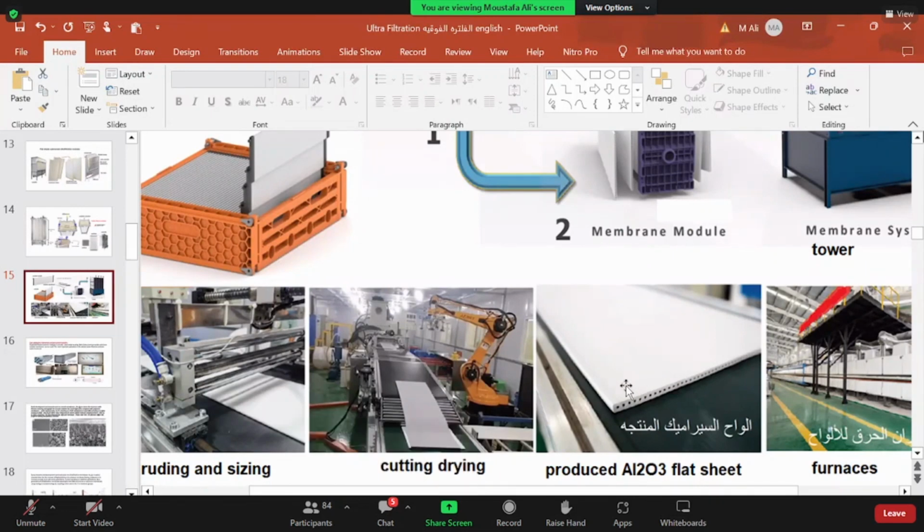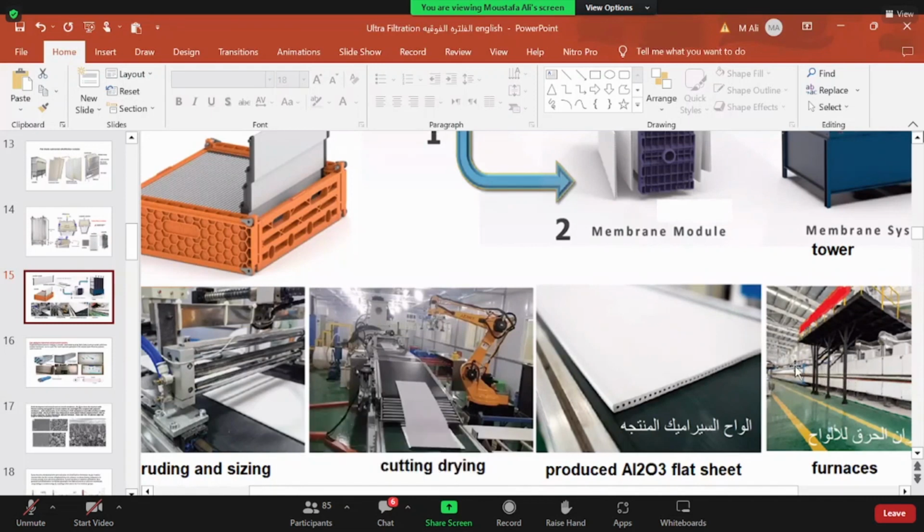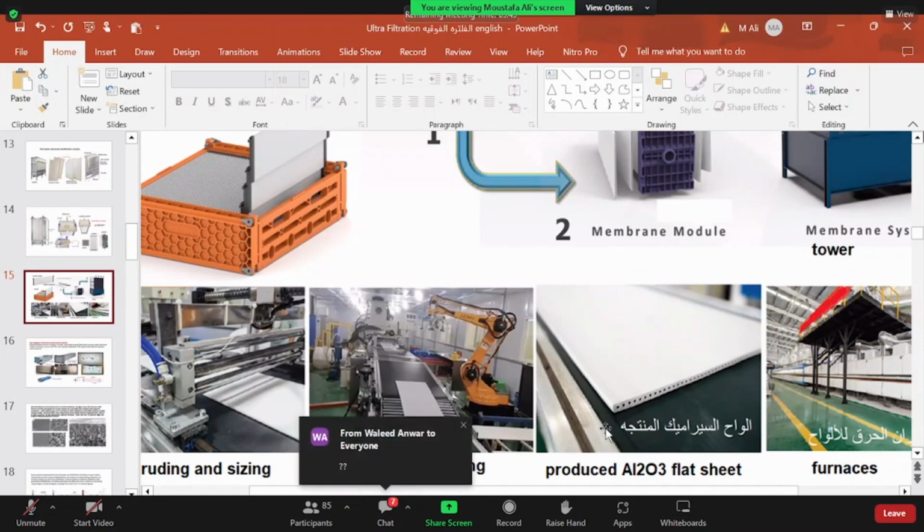The silicon carbide production process should not be in a very long furnace as shown in the figure here. No, it is just a compartment, a closed furnace. This closed furnace has graphite refractories inside, because it can tolerate up to 2000 degrees Celsius. The incipient melting point for silicon carbide is around 1800 degrees Celsius.